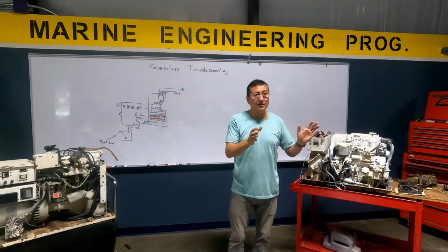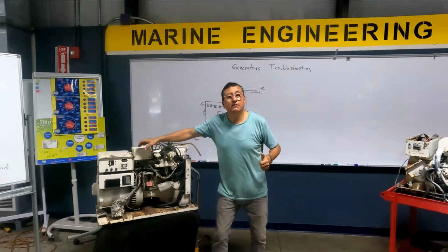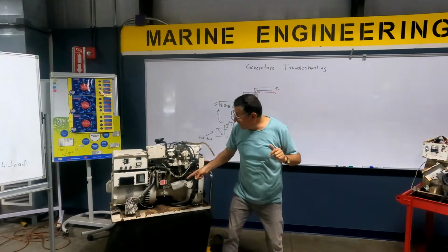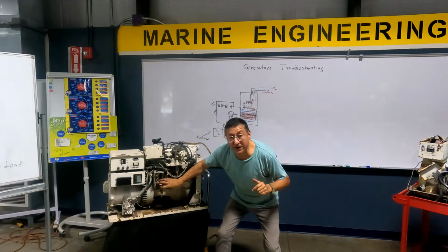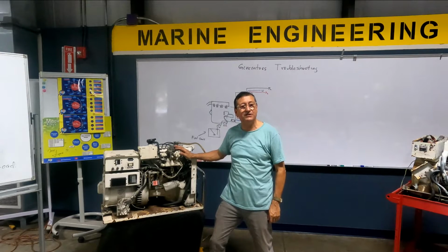That's in diesel. Later in the course of diesel, we are going to talk about that. But in gasoline, you have a similar issue with preheat. The preheat brings the fuel with the low pressure pump into the carburetor, in this particular case, because it's carbureted.